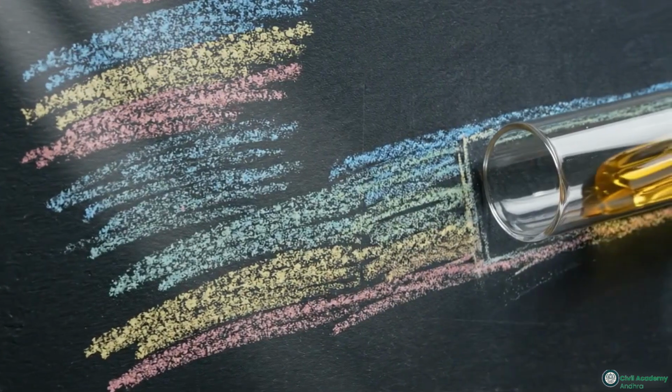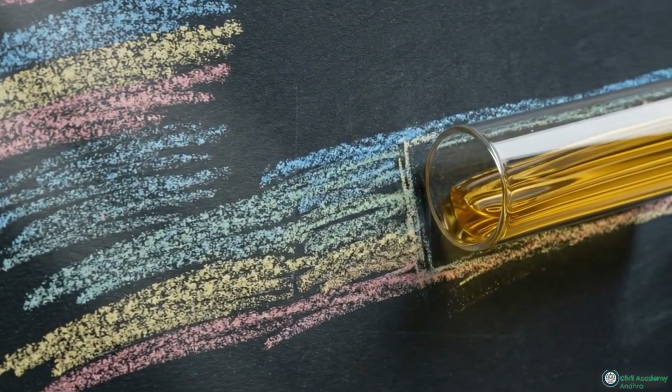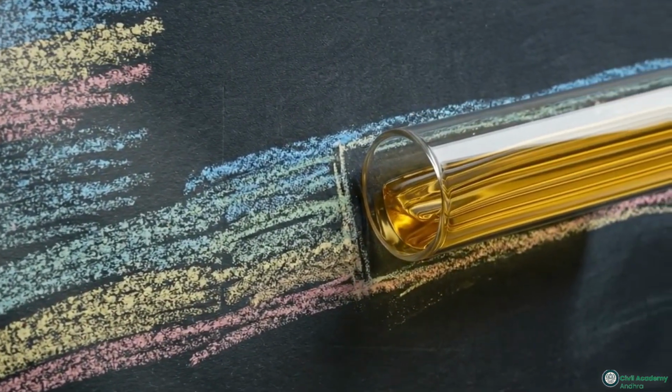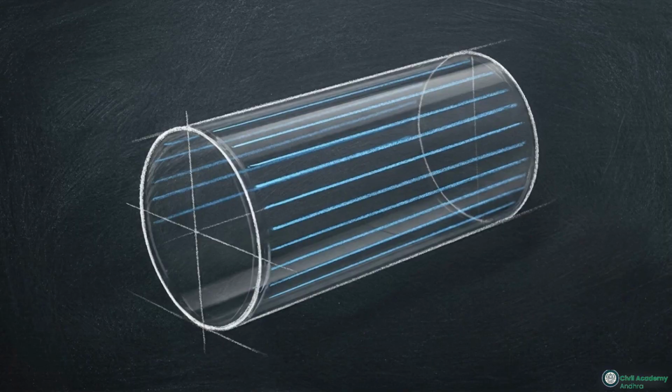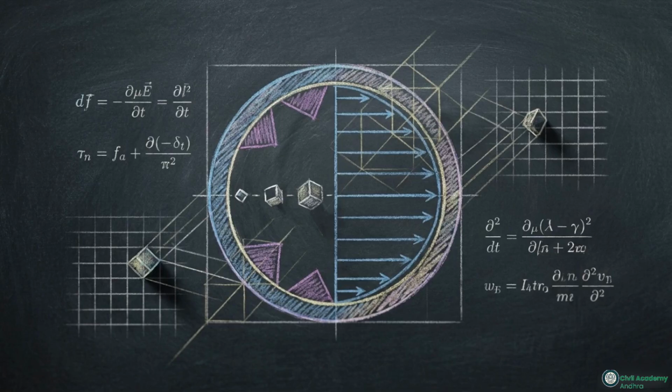Because these parallel layers do not mix, the mechanics of how energy is transferred and lost to friction behave entirely differently than in turbulent systems. This absolute viscous dominance allows us to model pipe behavior using exact mathematics rather than relying on empirical estimations.